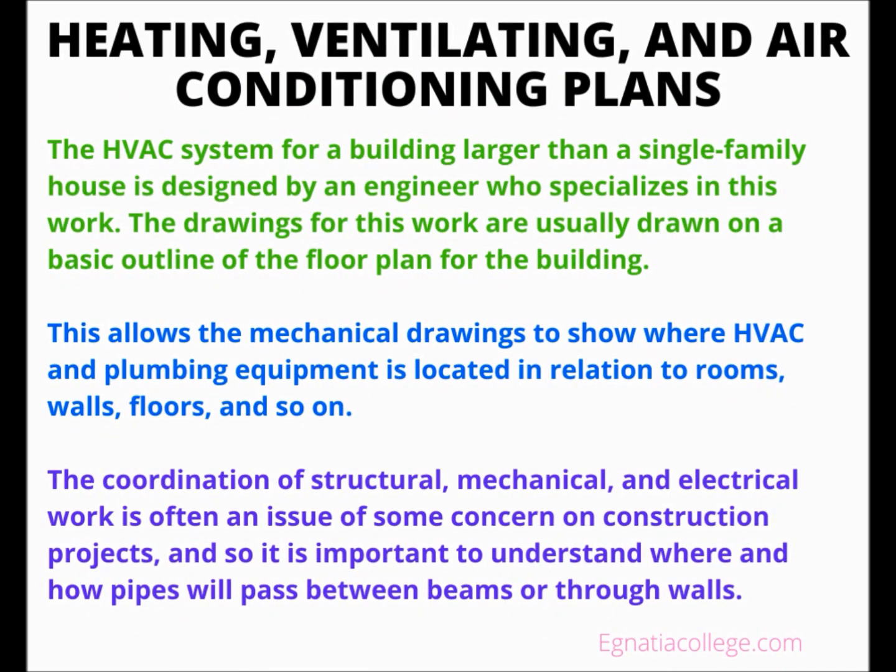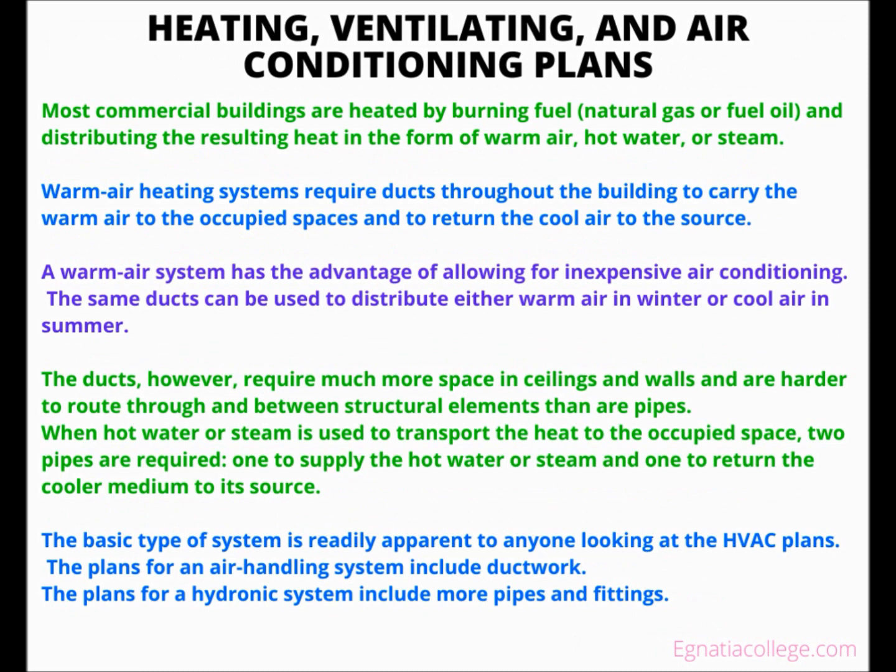Heating, ventilating, and air conditioning plans. The HVAC system for a building larger than a single-family house is designed by an engineer who specializes in this work. The drawings for this work are usually drawn on a basic outline of the floor plan for the building. This allows the mechanical drawings to show where HVAC and plumbing equipment is located in relation to rooms, walls, floors, and so on. The coordination of structural, mechanical, and electrical work is often an issue of some concern on construction projects, and so it is important to understand where and how pipes will pass between beams or through walls.